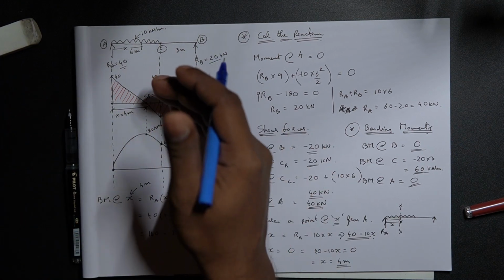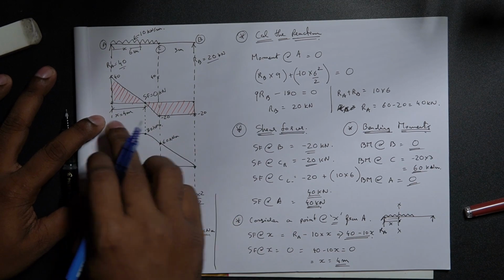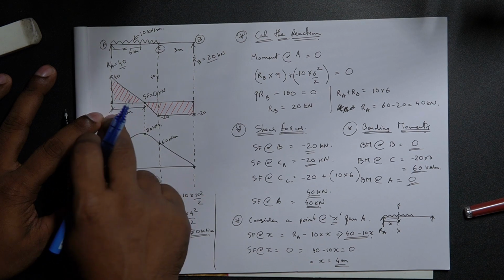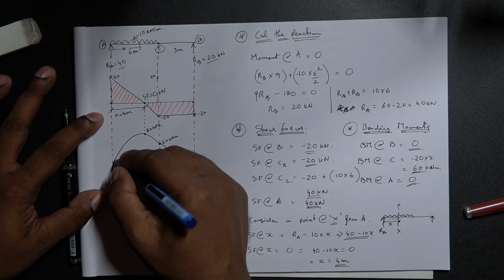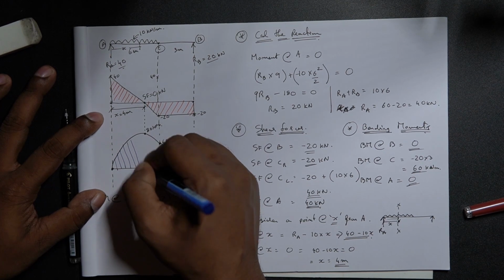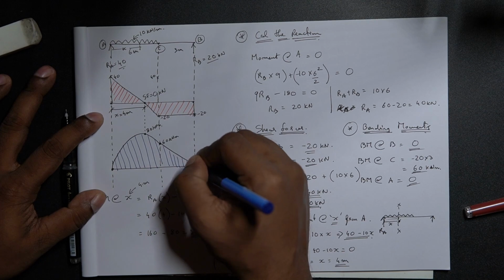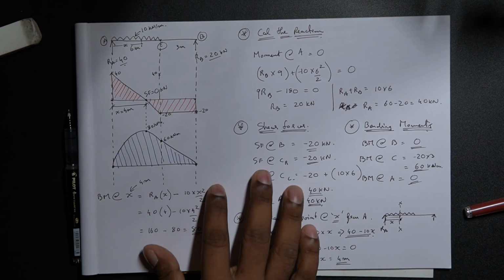At 0 shear force, the maximum bending moment occurs. In order to find the maximum bending moment, we calculate the distance between the support and the point where the 0 shear force is actually happening, and that is how we extrapolate the line to the moment diagram. So this is how you do this particular kind of example.